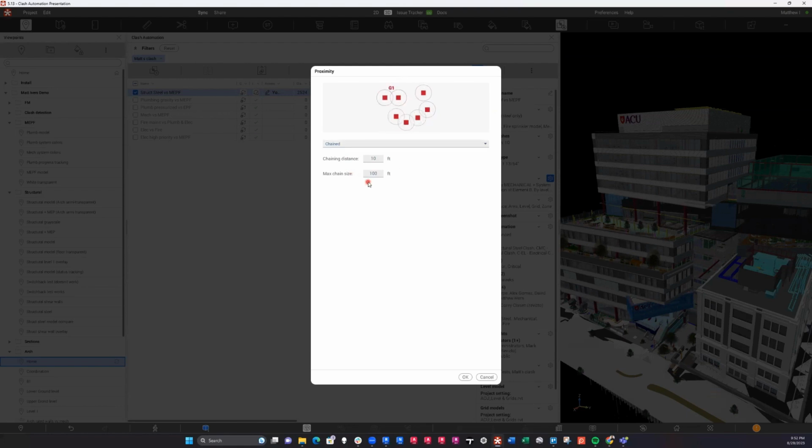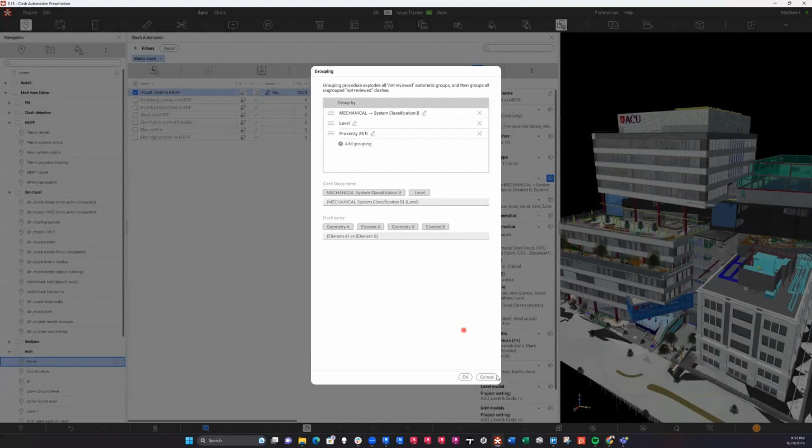So, I mean, that's really good for any things like, when you got a ton of clashes, let's say down a corridor, you know that that's gonna kind of be in the same row of clashes. That might make sense to chain that. But I'm gonna go ahead and stick to the regular. And I set that normally at around 25. Some people will bump it up some more.